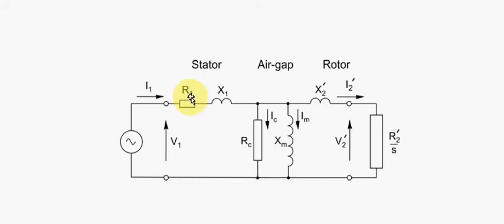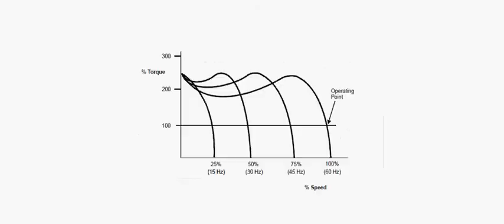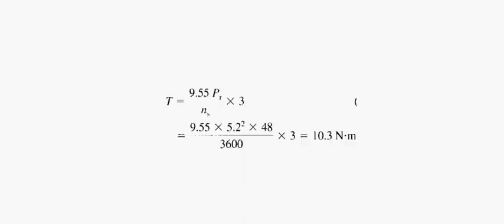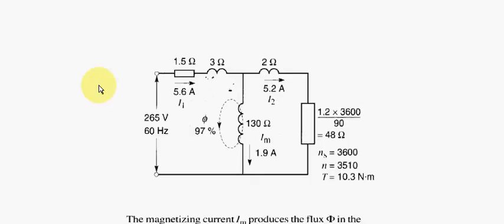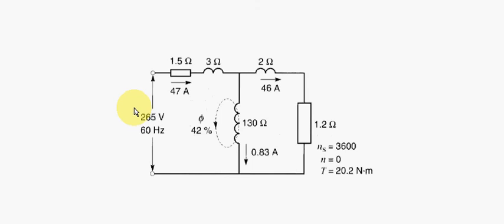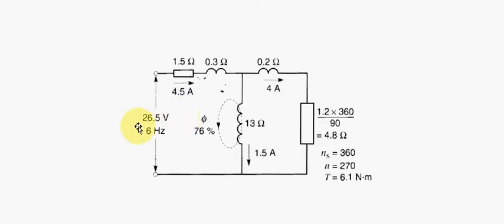So the majority of the current would flow down here. So in other words, the stator current would represent the magnetizing current as well. And if we know that, well, then all we have to do is up this value here, okay, up and up and up until we read the no load current at this point over here.